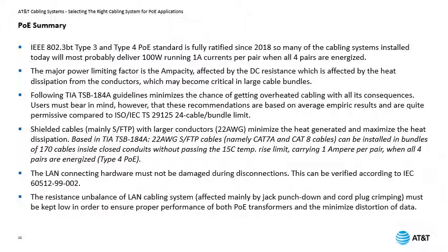Following TIA TSB-184A guidelines minimizes the chance of getting overheated cabling with all its consequences. Users must bear in mind, however, that those recommendations are based on average results and are quite primitive compared to ISO/IEC TS 29125, which recommends 24 cables in a bundle as a limit.